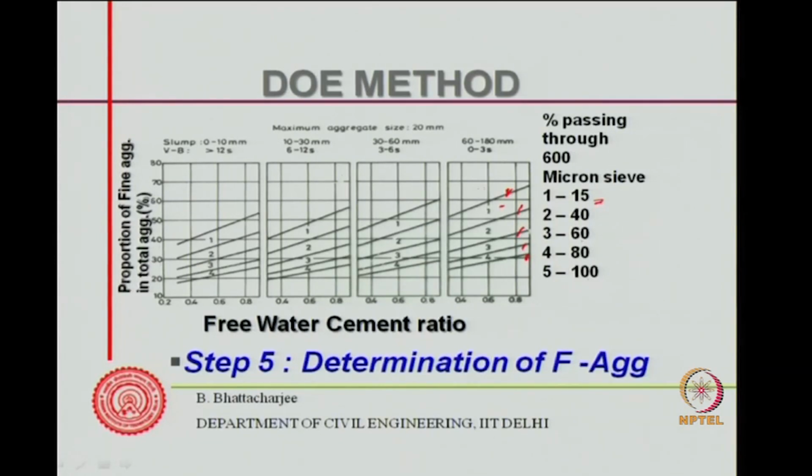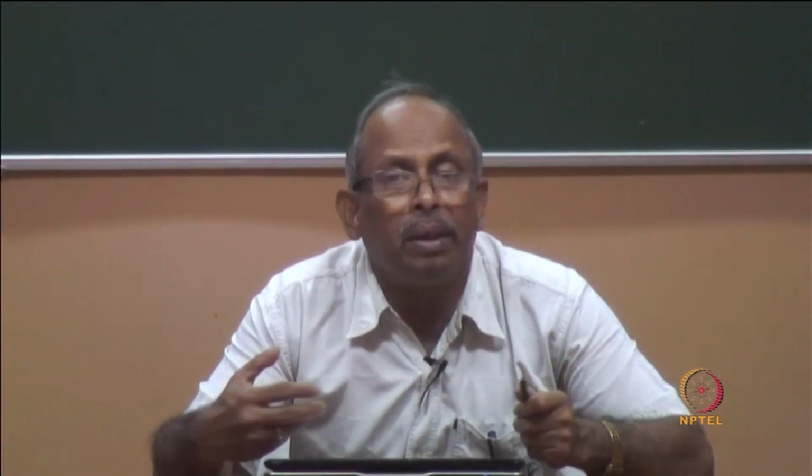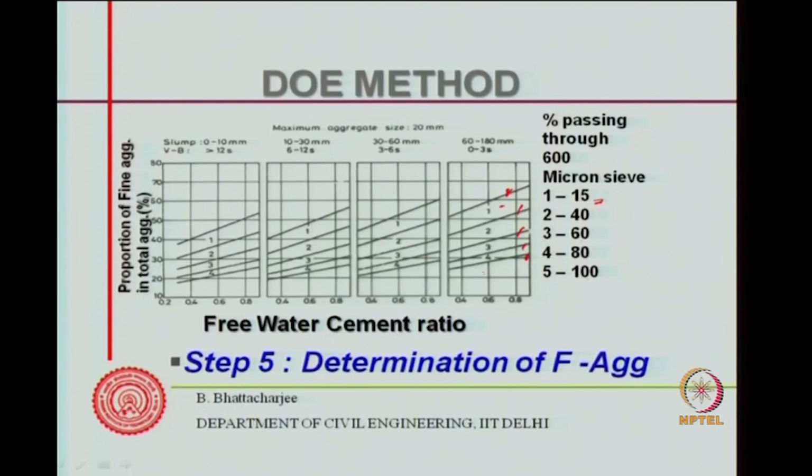So, therefore, fine content increases as we have coarse material in the system, because then coarse aggregate will reduce, fine content will increase. When fine is very fine, then you have got the maximum amount of fine to use, and this also depends upon the slump. For a higher slump, you need more fines, lesser coarse aggregate. This is understandable, because as I told you, coarse aggregate do not contribute to moldability. It is the paste and then the mortar and their flowability that contribute to the workability.